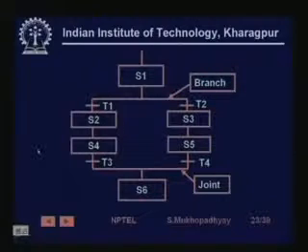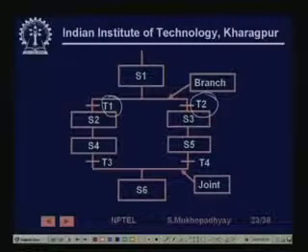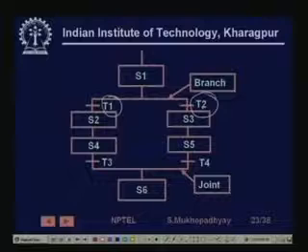For example, you can describe several kinds of programming constructs. Here is a case where, while the system is at S1, T1 and T2 are active, so any one of them can become true. If T1 is true, the next active state will be S2. If T2 is true, the next active state will be S3. It could conceivably also happen that in a given scan T1 and T2 both become true. In that case you have to resolve it, because both transitions cannot take place simultaneously. There is a convention that the leftmost transition takes place, so if T1 and T2 are both true at the same time, T1 is assumed to have taken place.